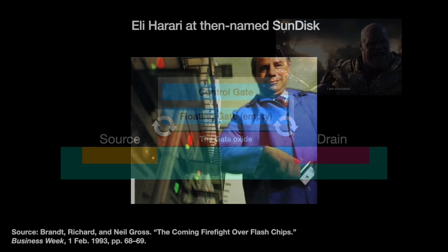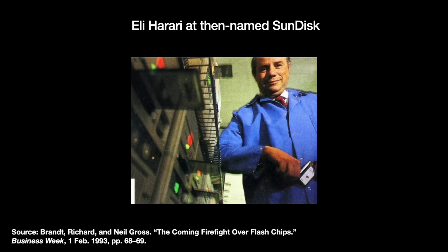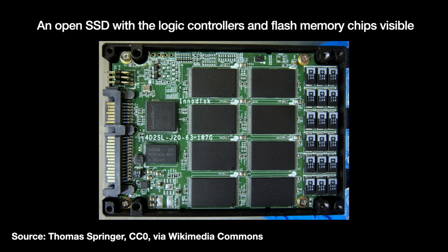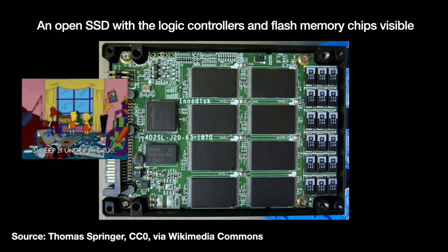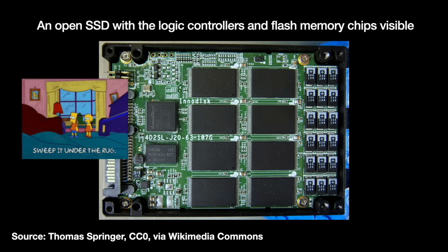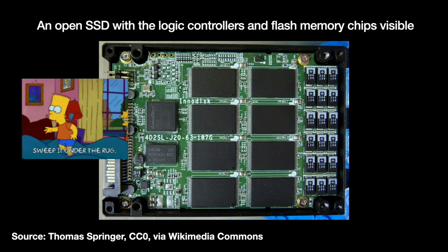Eli Harari and SanDisk realized that their only way to fix flash's inherent problems was to take a system-level, holistic approach. They combined the flash memory dies with an off-the-shelf embedded logic IC called a controller. That controller was programmed with error correction software to detect and handle errors, as well as procedures to lengthen the drive's overall working life, like spreading out wear across the multiple flash dies. In the end, all the PC sees is just another disk drive, a solid-state drive, so to say. All the hairy things gracefully swept under the rug.